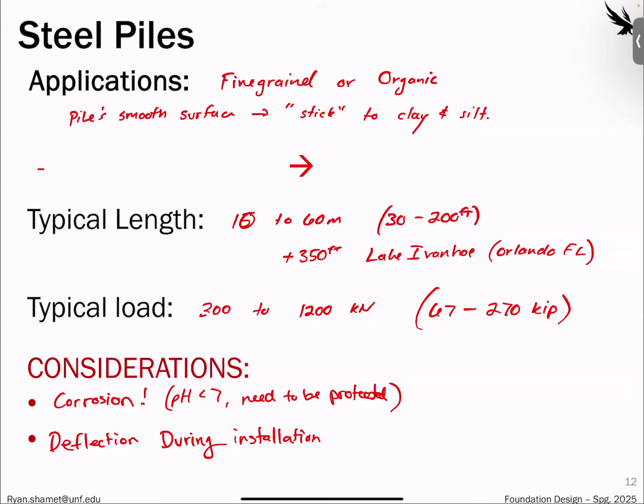Yeah, there's different ways of testing it. Usually you know where the soil layers are underground from testing. So you know, okay, at this depth we should have some resistance, or we should have hit rock by now. That's one of the ways. Another way is seismic testing on the pile. You stop driving and hit the pile, and you have geophones or some types of sensors around the ground. And if you're getting pings over there, then you're like, oh crap, that pile's traveling that way.